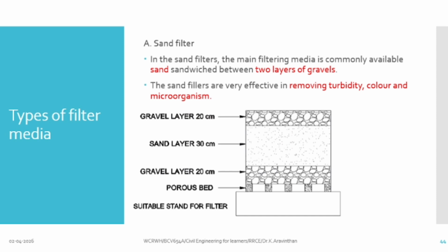Sir, how should the filter be? A rainwater filter should have only three materials. What are they? It will be like a sandwich. Inside the sandwich you have some vegetables or cheese, and top and bottom you have the bread. The same way, top and bottom you have this kind of gravel. Gravel or coarse stones, of higher diameter. You should have gravel at top and bottom. In the sandwich part you should have sand. This is the way to filter. What will happen if the rainfall is directly falling in this place? It will get filtered and it will go to the tank.